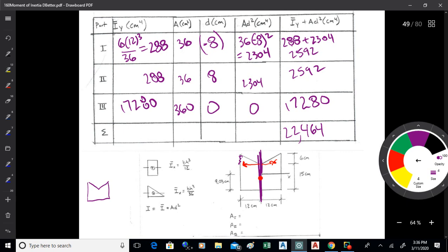I can point at a point and say that's the centroid, but I can't do that for the moment of inertia. It's a more abstract concept. It's how well the beam would resist bending about a given axis, kind of about how much stress would build up in the beam in a given direction.